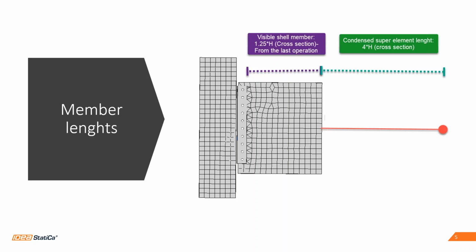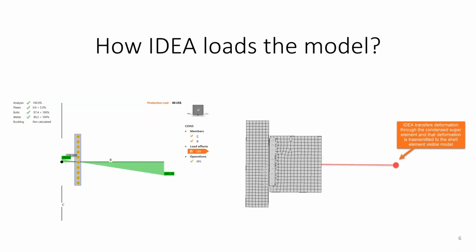Why are these lengths important? Those values are important to load the model, because IDEA StatiCa uses moments to load your model. For instance, from the shear force you input, we calculate the moments created by that shear force and use them to load and deform the visible shell model, and then get the strain and the stresses from it.